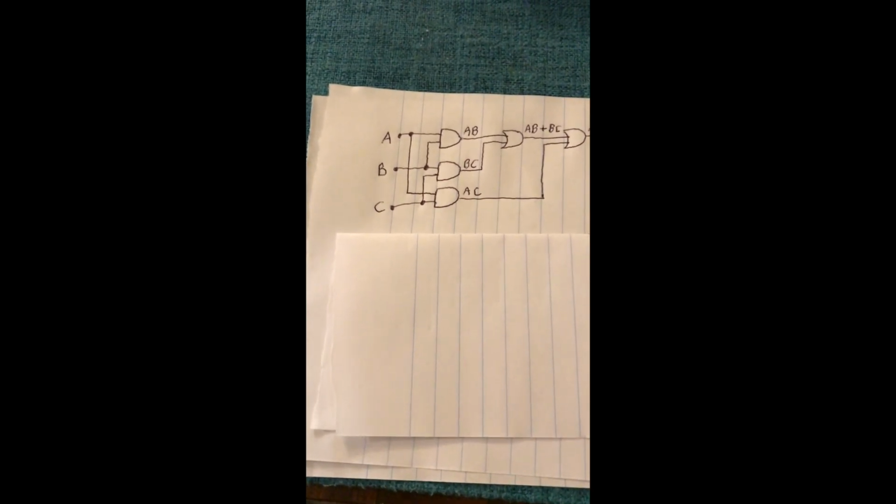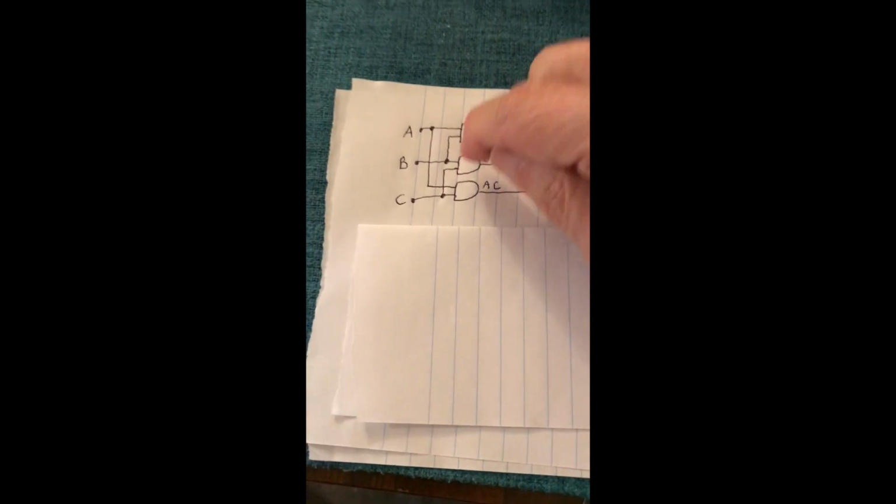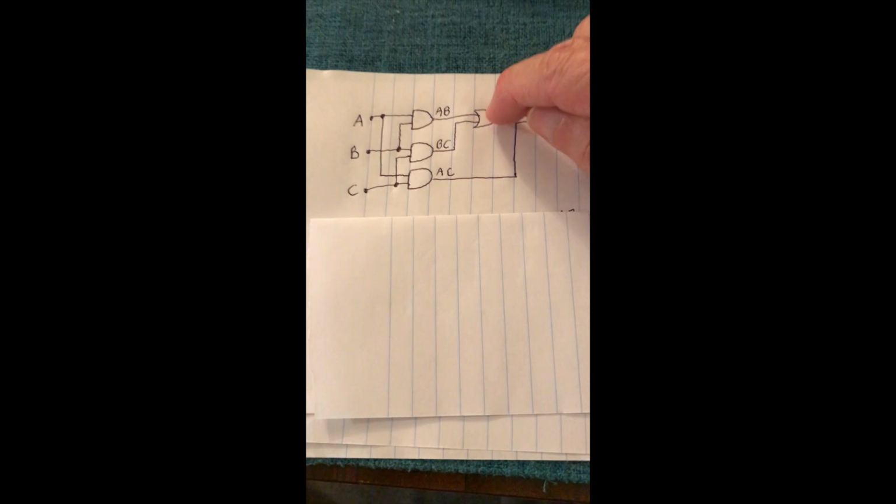And of course, if all 3 vote to turn on the light, then that's a majority also. But this is going to detect that because in that case, all 3 of these outputs are going to be on. And so certainly we're going to have that detected in the final output here. Since it detects any one of the 3, it'll certainly detect all 3.